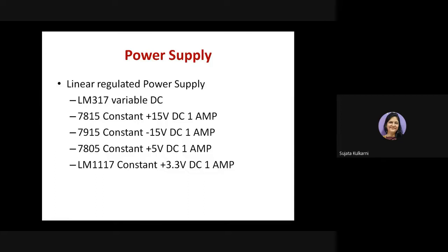But at the same time, size, power consumption, and flexibility and reusability are really worrisome for us. So somewhere we have to look at all these design constraints, and accordingly design our product. As I told you, if you go for an SMPS based power supply, you can save a lot of cost, but then the output won't be ripple free. Definitely there will be a ripple.